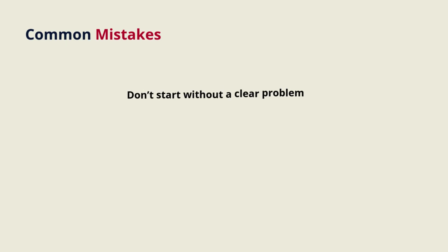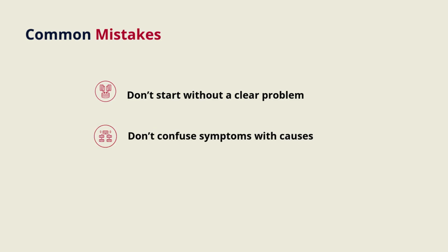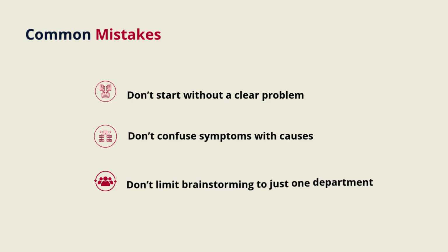First, don't start without a clearly defined problem statement. Vague problems lead to vague causes. Second, don't confuse symptoms with causes. A scratch on a part is not the cause, it's the result. Third, don't limit brainstorming to just one department. Quality alone can't solve it. You need production, maintenance, and design together.